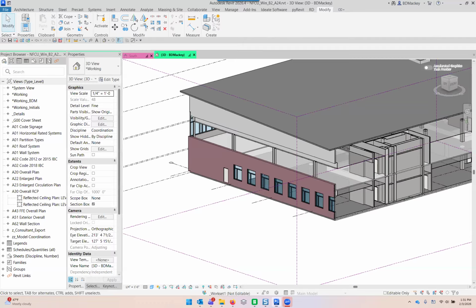I will say in Revit, there are sometimes with a type parameter where you might make a change and Revit doesn't necessarily recognize it, or tags might not recognize it. Oftentimes it's because Revit's got to rethink that element, and you would think hitting edit type would make Revit rethink the element, but oftentimes it doesn't. Sometimes if you nudge a window and then nudge it back, it makes Revit rethink it, so it'll rethink its tag and say, oh, that's changed, I should rethink it on tags everywhere else. So I've not noticed the parameters not sticking. Usually for me, it's more that I've got to get Revit to rethink to display it properly.